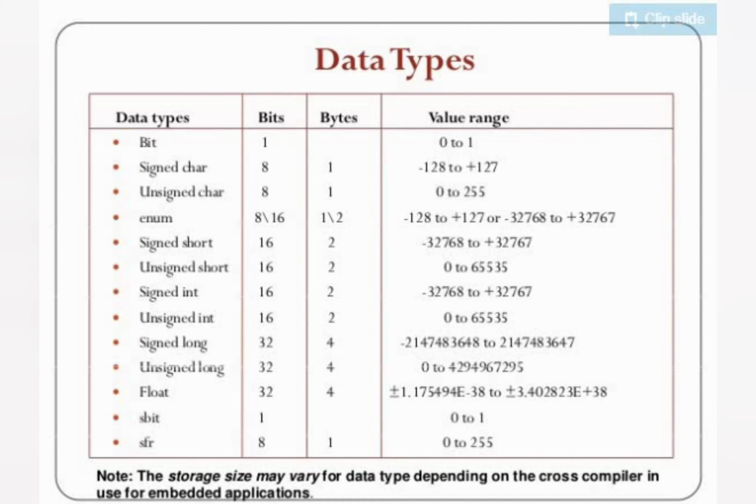Basically it is a frequently used unsigned integer, and here unsigned characters range 0 to 255. Otherwise you can choose as per your requirements. SFR is basically used for the special function registers. Its size is 8 bit and the range is 0 to 255.